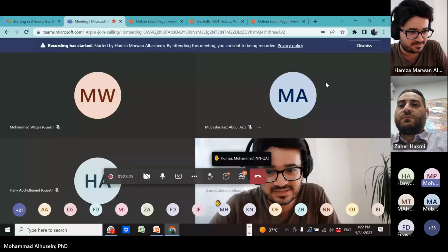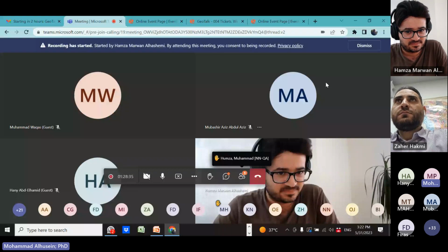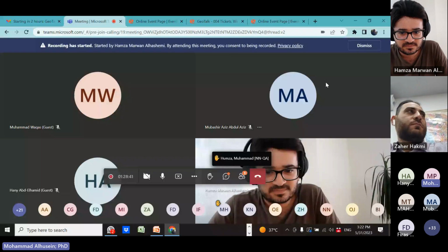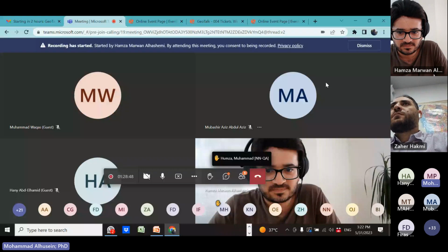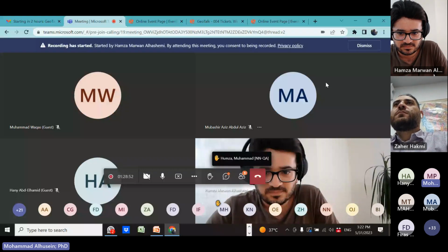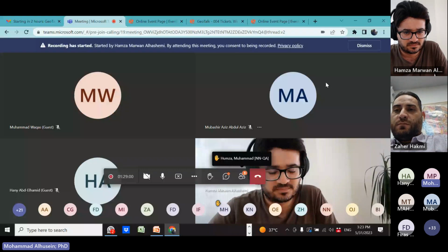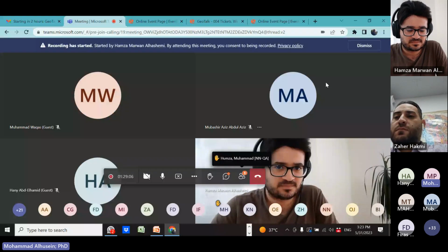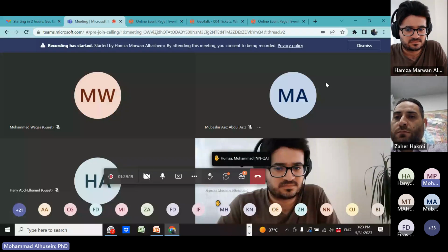I think I answered this question during the presentation. Unfortunately, there is no relationship up to date and no software up to date, and we have to rely on judgment and also on chemical testing, which tells us the percentage of this material. Then you have to do some mechanical or physical improvement. And then we can rely on software to do the modeling, with the structure or infrastructure supported by artificial elements embedded into the soil, which are the columns created by jet grouting or soil mixing, etc.